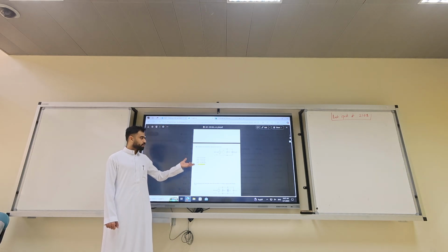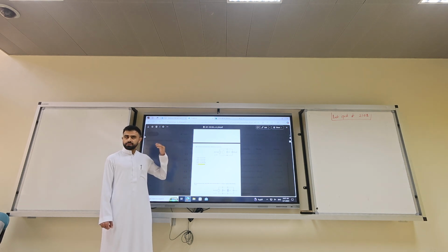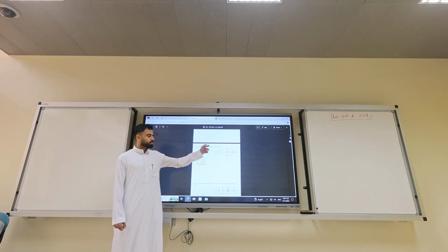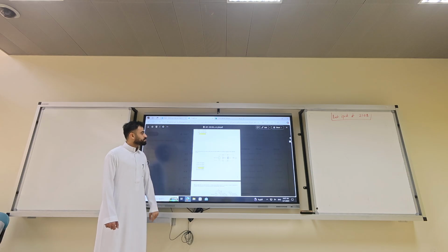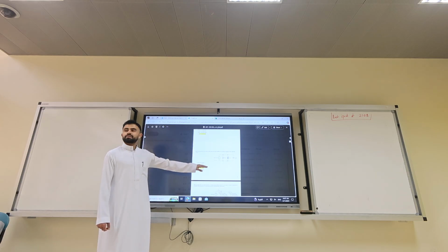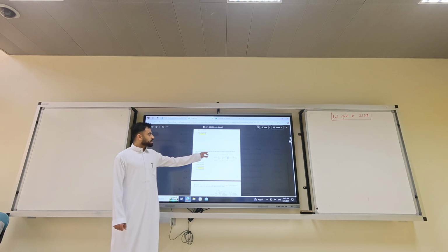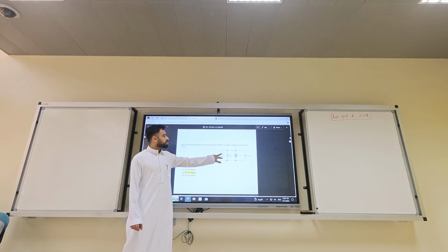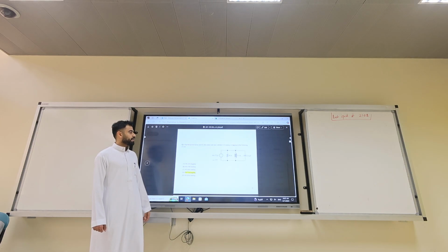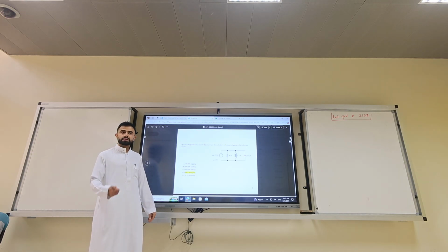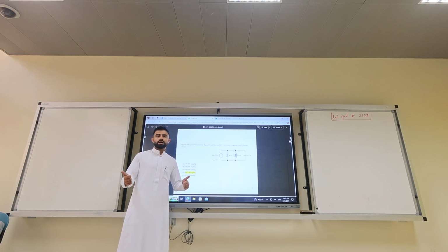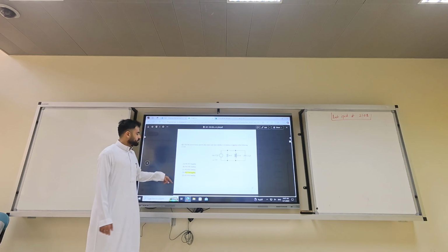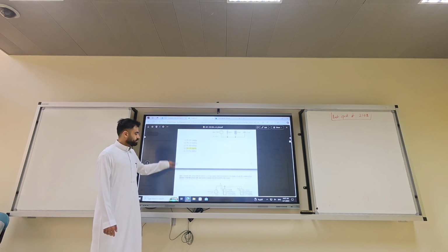Once you calculate the complex power, for example, you get S equal what? 1 over 2 V I conjugate, then you can calculate Q. Okay? Look at this problem. Chapter 5. Find the power factor seen by the source and state whether it's leading or lagging. It means you have to find the current. Once you find the current, the angle between the voltage and the current gives you the power factor. And which one is leading, which one is lagging, you have to plot it, okay?